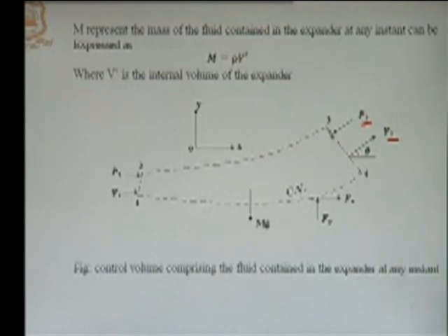Now, in this control volume, we have the weight of the fluid which is acting in a downward direction, and that weight of the fluid is acting through the Cg of this fluid element, and that weight can be calculated as the volume of the control volume multiplied by weight density, and simply it may be written as mg.